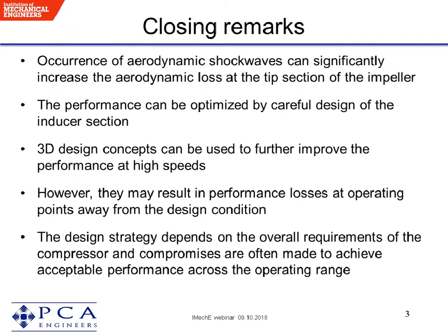Me too, Mick. I mean, in centrifugal compressors, the common approach is passive enhancement methods, casing treatment, and in some cases, upgradable material on the casing. I personally don't know of designs with active clearance. I'm sure people tried it before, but I have no knowledge of that. Yeah. I've seen it in practice, but it's confidential.